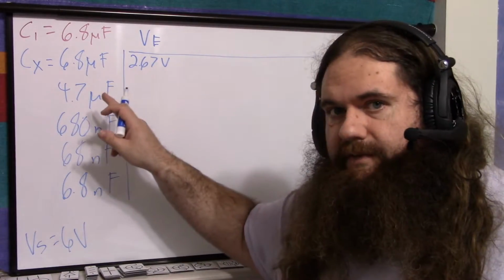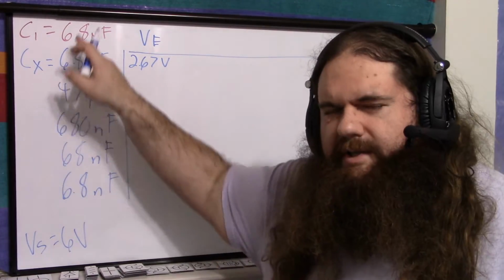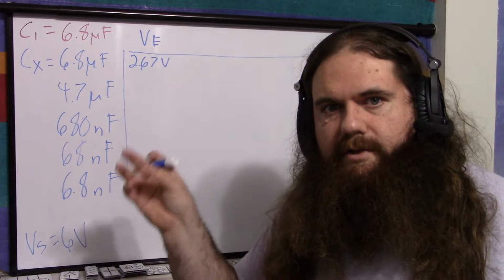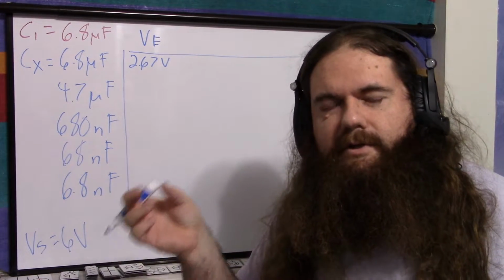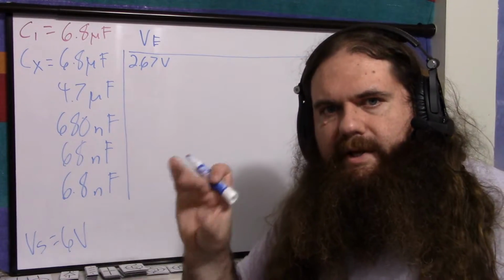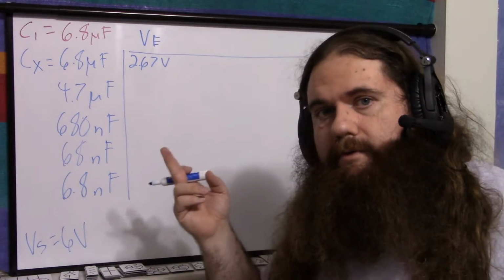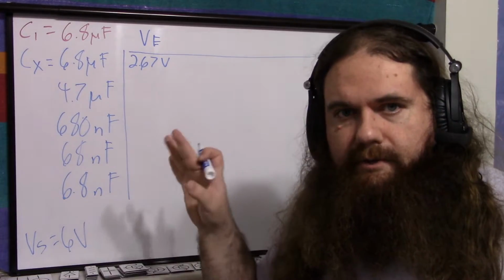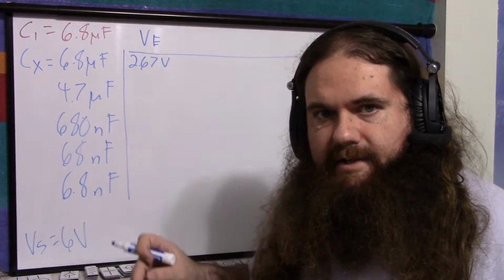So you can already see the variance because it should have been 3. Because the capacitors are the same capacitance, so they should have shared the charge equally, so they should share the voltage equally. They should equalize to be half the supply voltage. So 2.67 is reasonably close to 3, but anyway, like I said, that's the variances at work.